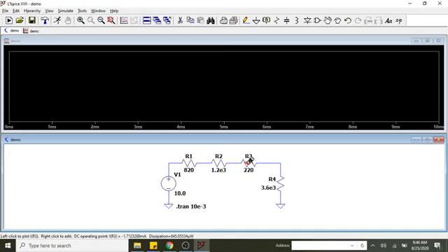Now, one thing you'll notice here is a current showing up as negative. And the reason for that is if you look at your cursor, you can see that the arrow is pointing to the left over each resistor, and it's pointing up on the R4 resistor. And we want these to be pointing in the actual direction of conventional current. This is showing electron flow, and we want this to show conventional flow.